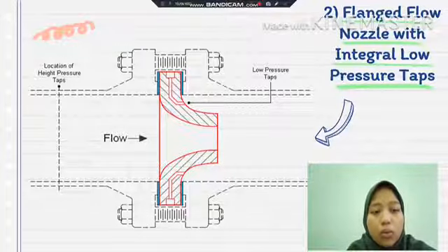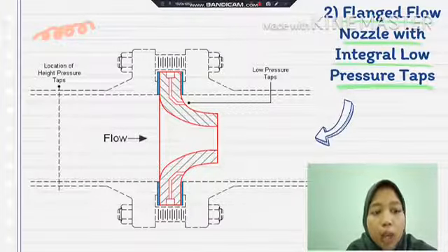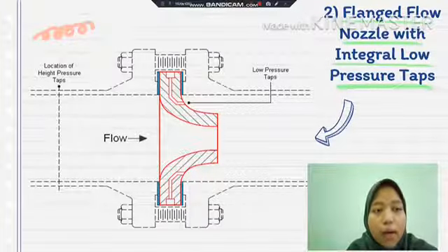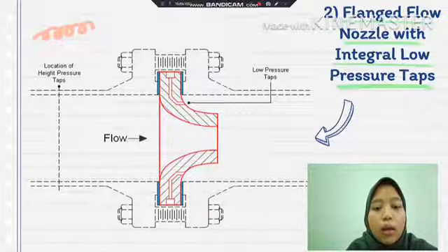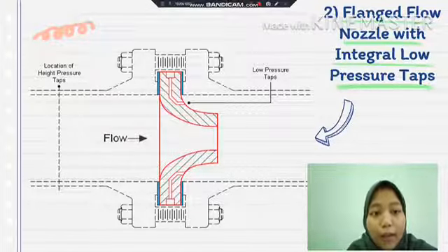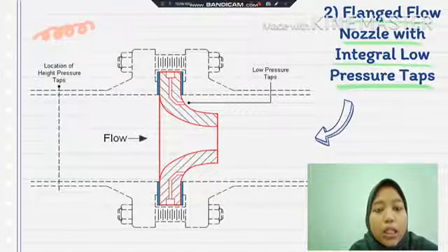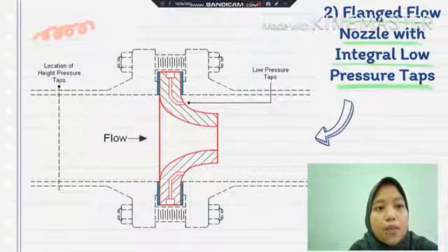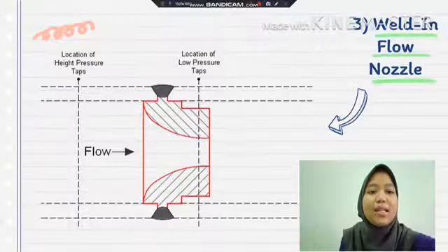It can be used in smaller pipe sizes where the low pressure tap may interfere with the pipe weld, flange or flange bolting. The low pressure connection most used is 6 mm unless specified otherwise.